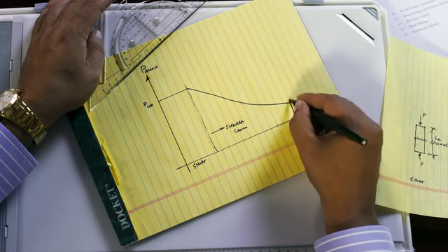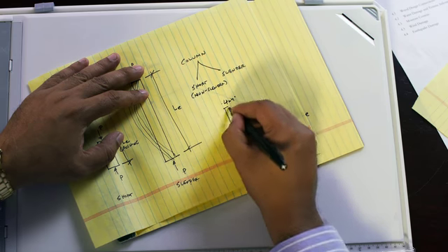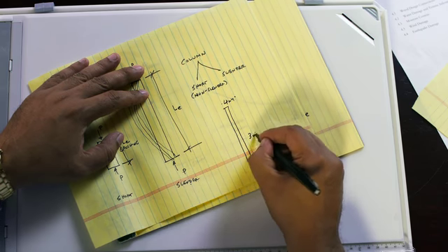And then there's usually an upper limit. You can't go past that upper limit, and that depends upon the type of wood. I haven't put any numbers in here because I'm just giving you the concept. But you can't have a column which is, say, a 4 by 4 that goes 30 feet, for example, because it's too unstable. You've got to put in some lateral bracing. So there's a limit on how far you can make a tall column.